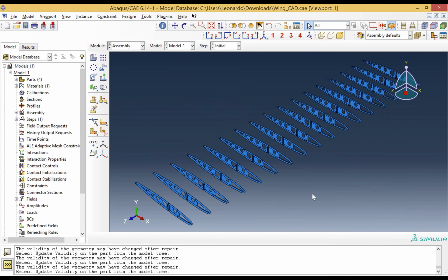All right, when this has been done, we need to modify the depth of the extrusion for the remaining parts, because this linear pattern has extended the span from 4,000 millimeters to 4,020 millimeters. So we need to modify this.